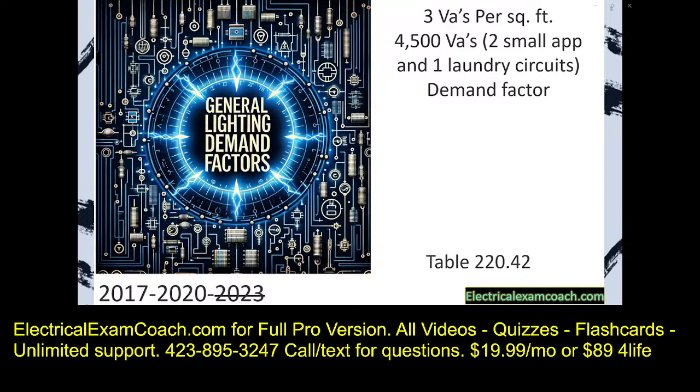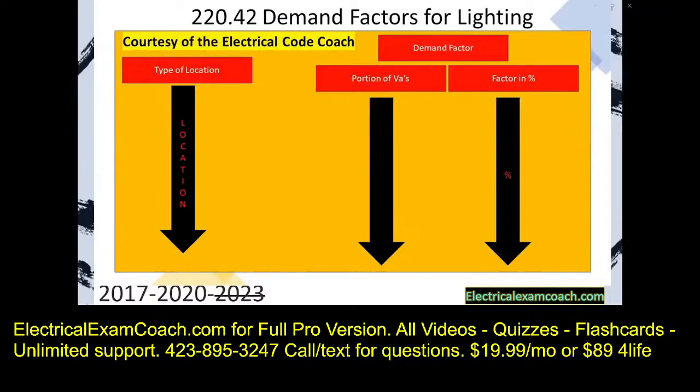And for this one, we're going to head to table 220.42. It's a very important table in our load calculation process. When we get to table 220.42, we always read the black bold heading to make sure that we're in the right table. And it says demand factors for lighting. Now, you can ask the question, if this is the 3 VAs per square foot, well, it includes receptacles. And you are correct. We are allowed to use this table for commercial lighting or any of the lighting in the following locations that we're getting ready to talk about. But we're also allowed to use it for the entire 3 VAs per square foot, plus the 4,500 that we tacked on for the 2 small appliance and 1 laundry.